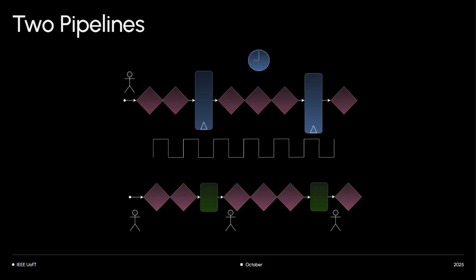Although there's a saturation now. There's a recent Nobel Prize in physics for quantum tunneling, which seems to unlock some quantum tunneling effects, which I don't even know much about. But what is happening is we're saturating at 2 nanometers right now because of quantum tunneling effects. Charges leak through the gate, and it's not really a transistor anymore at that point. But deviations aside, the smaller your gate is in terms of feature size, or number of transistors, the lesser the propagation delay.